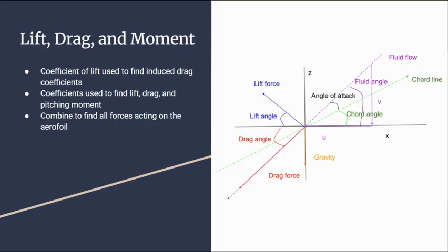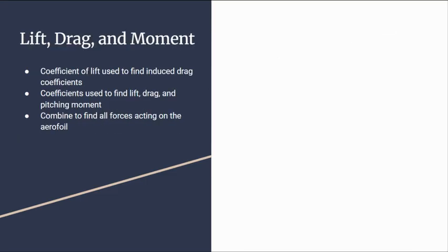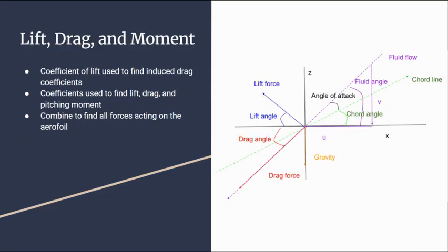Once the boundary data is processed, the code automatically scales everything to the correct chord length and converts the spline into the mathematical form needed for the aerodynamic integrals. Now, one limitation of thin airfoil theory is that it assumes inviscid flow. That means drag cannot be computed directly. This is a consequence of D'Alembert's paradox.